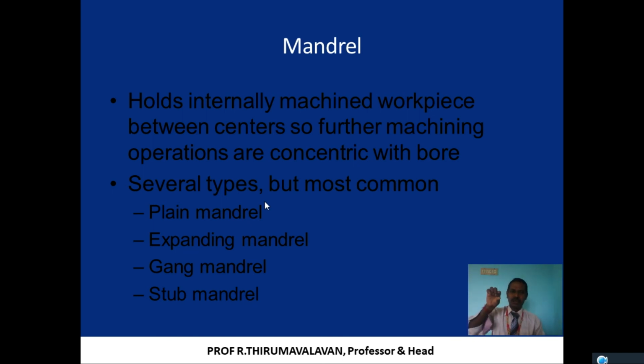A mandrel is nothing but a stepped job, like step turning on the lathe machine. The internally machined holes of the workpieces are held between the centers, so further machining operations are carried out concentric with the bores. Several types of mandrels are there: plain mandrel, expanded mandrel, gang mandrel, and stub mandrel. 4 types of mandrel.